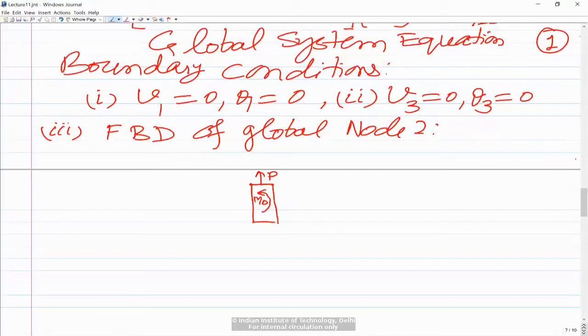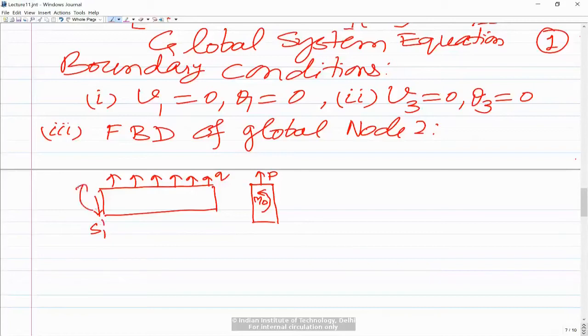Now, because we are drawing the free body diagram of the node, we will get the forces from the element. If you look at the element on the left of this node, and at the free body diagram of the element itself, on the left side you have S11 and a bending moment M11. The coordinate directions are x and y, with z coming out of the screen.